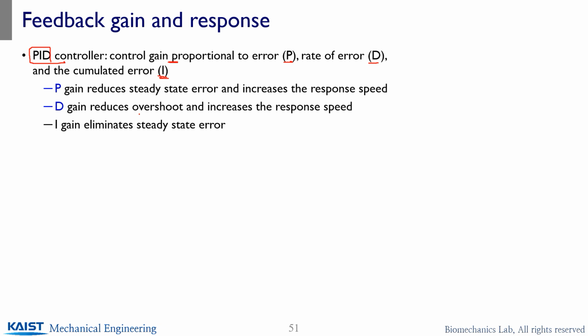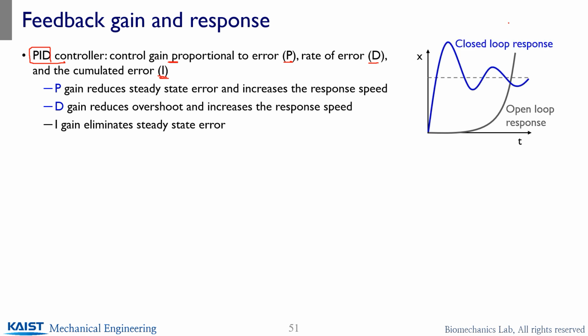So you can think about, yes, that if you increase the damper, the system will be less oscillatory and reduce the overshoot. Okay, so for the inverted pendulum, the open loop response definitely diverges, and if you apply some PD controller, it will actually converge to a certain value for the step input. And if you want to reduce that overshoot, you can actually increase the D gain, etc.